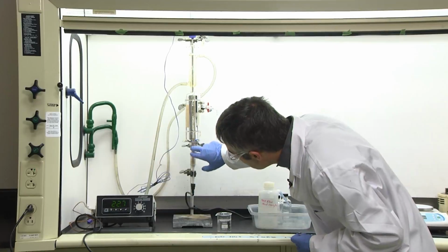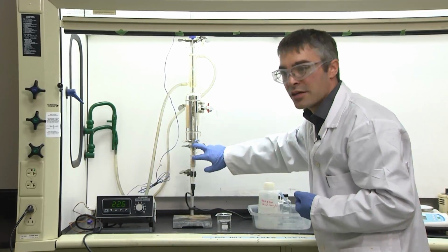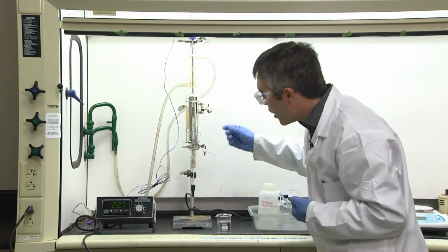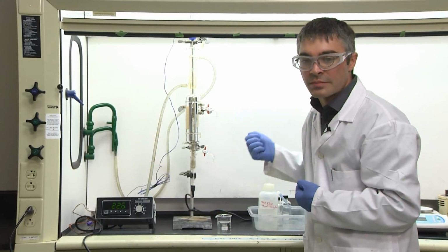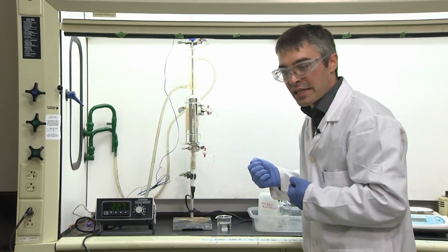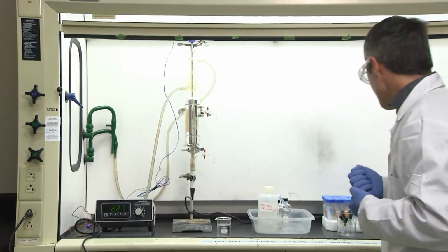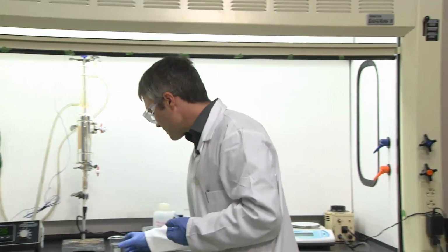It is a packed sand around an electrical output. Again, if this is allowed to cool down or expand too quickly, if the load is too hot, it will crack. And if it cracks, you'll be exposing bare resistance wire to whatever vapor that you're concocting, which is potentially explosive. The operation, once you have everything going, is fairly simple.